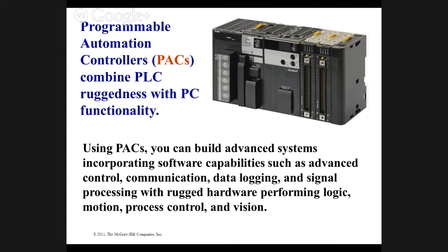That up there is actually called a PAC. Yeah, that's actually called a PAC. It's the new buzzword because it has a lot more bells and whistles. And you can even, not that brand, but you can even get PLCs where the touchscreen and the PLC are one device. So you program the PLC and the outputs on the back of the HMI, so it's just one box with a touchscreen and everything sits to the back.